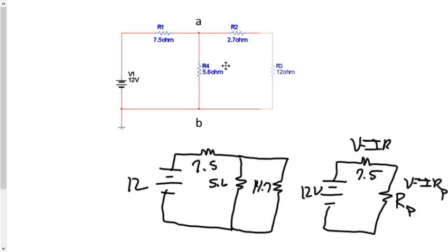And then unravel one more time to get this. You'll have the current through both of these being whatever you found here. And then use V equals IR to get the volts on this one. And V equals IR on this. The I here is whatever current you found here. And then you'll have volts and current on this, and likewise. And then you use P equals IV to get the power on each of those resistors. And that's how you do it. And if you have any other questions, come see me in class.